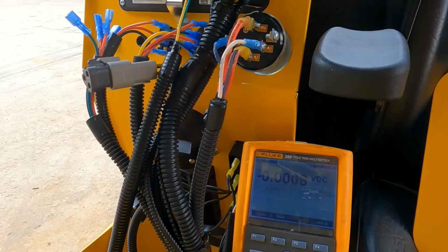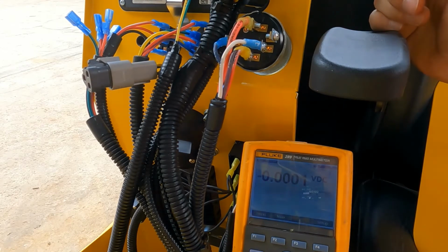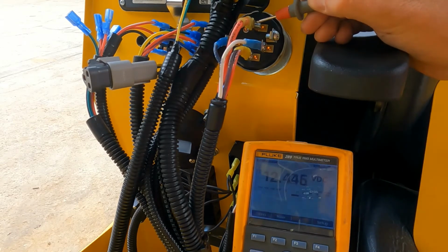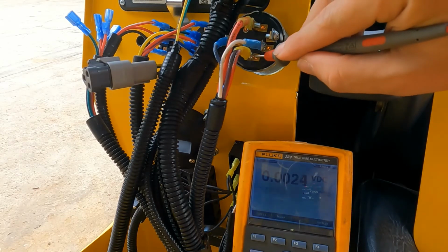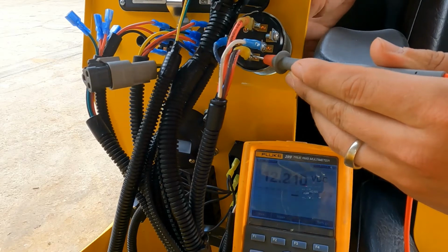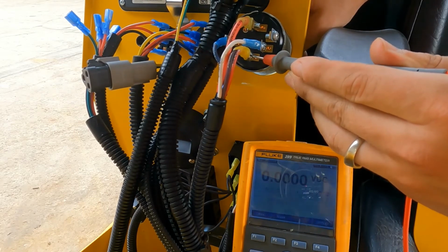So now we need to locate the power, the ground, and the ignition wire on the machine. This is very important as it helps us program our sleep functions and make sure that we do a proper shutdown on the box. So here we have constant 12-volt power, on or off no matter what the machine is. And this one here, we've got an ignition wire that is on and off with the key switch that you see here. This is very important to make sure that we wire this up and not just kill power directly to the box.